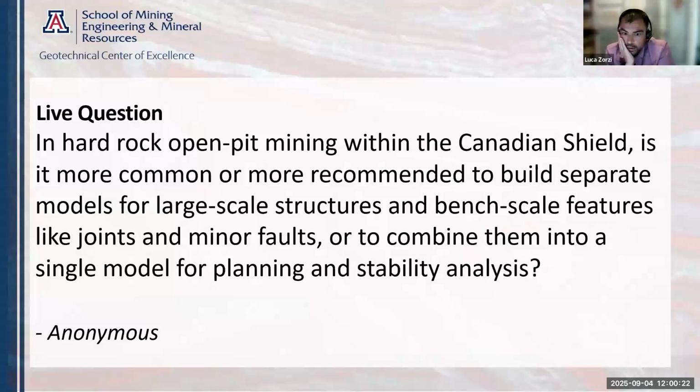Okay, to answer this question, I'll go personal. I normally create a single model because every structure is part of the same system, without getting too crazy with the minor faults or the specific joints, but there is a relationship between faults, joints, and geology. So I tend to go for a single model, which then has the ability to be broken down based on the end user. So you go with a big model on the assumption that the model is used for detailed slope design. Because if it's just for early stages, then I would just stop at the large-scale structures.